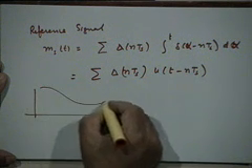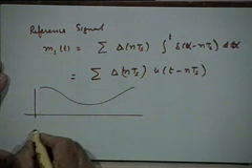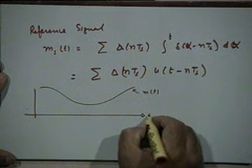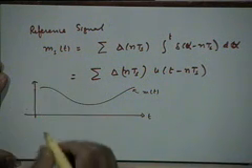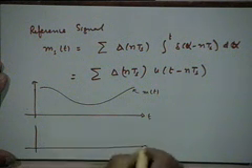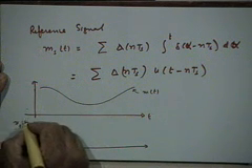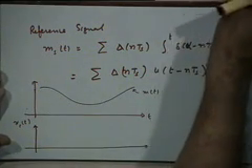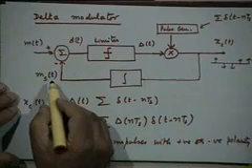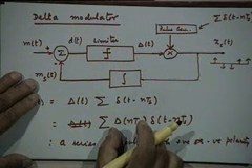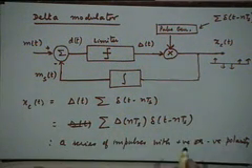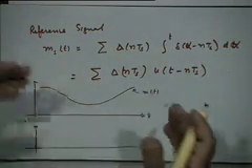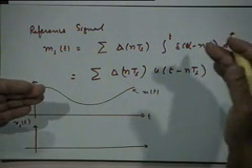Let us say this is your signal, right? This is your message signal m(t). And here I will draw the modulated signal x_c(t). Let's assume for the moment that in any subinterval of T_s seconds, the value of m_s(t) is going to be constant, isn't it? It's basically a step that comes in, and the value will remain constant till the next step comes, right?